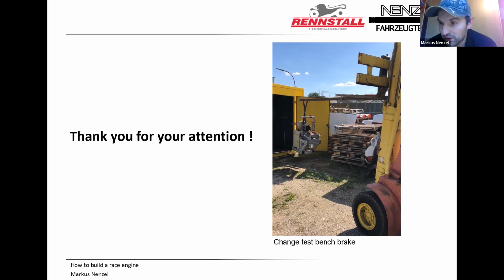Maybe the hardest thing is, if you want to do traction control, for example, you have the two which are not driven in the front, you can average, then the rear average. Then you have this slip which you want to kill with your ignition, for example. Maybe more tricky is that you need information about your tire temperature, about the mu of the test track.